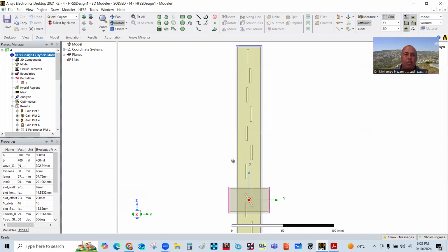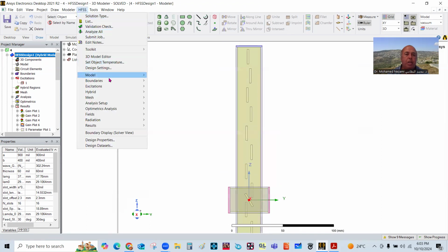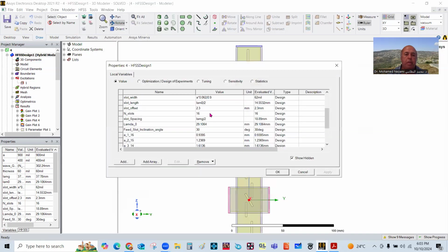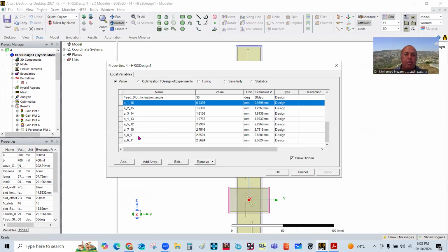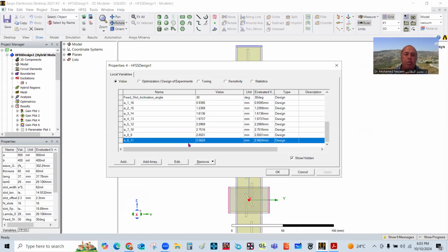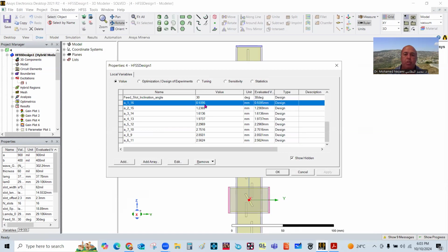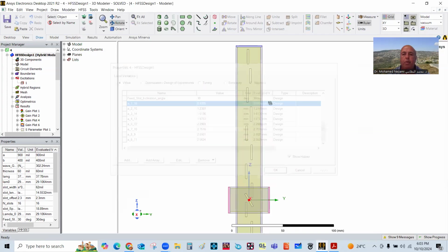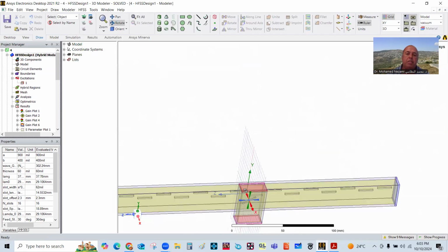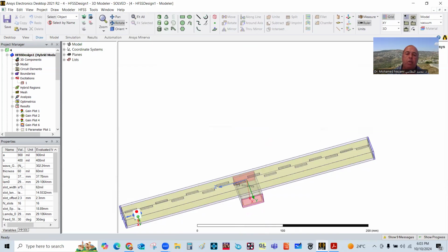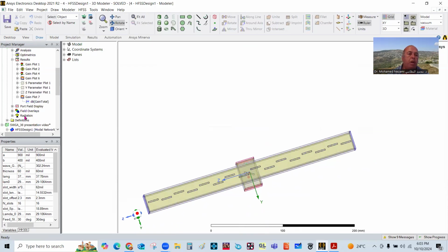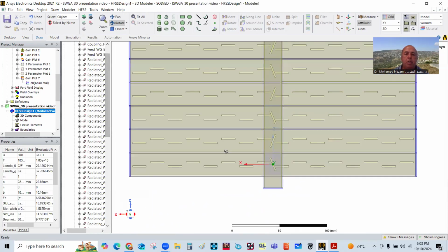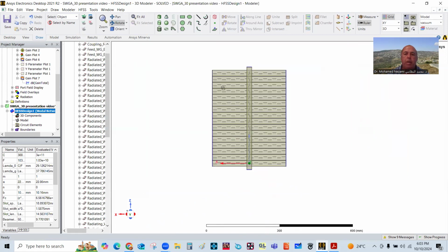These are the coefficients. And of course, the coefficients are generated from MATLAB, and they're right here. You can see we started out in the middle at 2.5 millimeter all the way to the end side, which is roughly 0.94 millimeter. Now, this is easily done for a single waveguide. However, for an array aperture like this, it's a little bit more complicated.